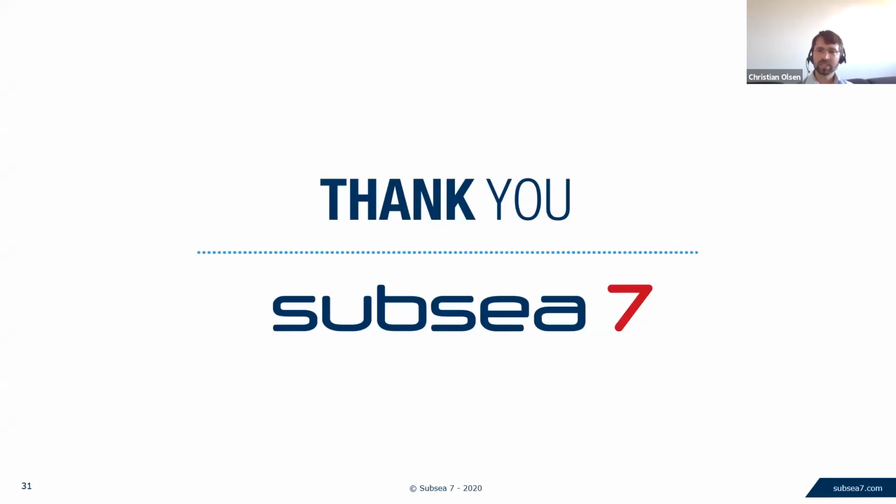What I've experienced is that if I need to reduce the load of a structure in PLAXIS while it's subject to torsion, then sometimes it becomes a bit unstable. And maybe it's my lack of experience working with this problem, but load path 1 has always been difficult for me to do. So maybe if you were to go for load path 1 and you had more experience than I, then you could make it work quicker. But I've chosen to use load path 2.